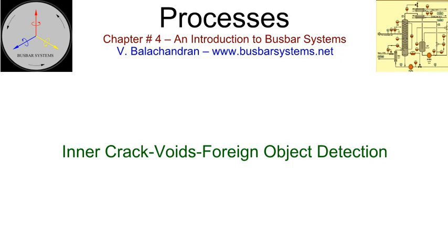This test is possible when both sides of the weld are accessible. Radiographic interpretation requires skill and experience in the field. A false interpretation can be very expensive. A radiographic test provides a permanent record of the test. It is essential that trained and qualified personnel, who understand the procedures and health and safety issues, conduct the test.